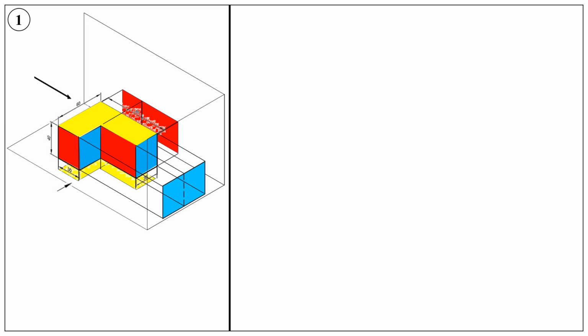Just now we discussed front view will be above XY line, top view will be below XY line, and the left hand side view of the object must be drawn on the space which is to the right side of the front view.